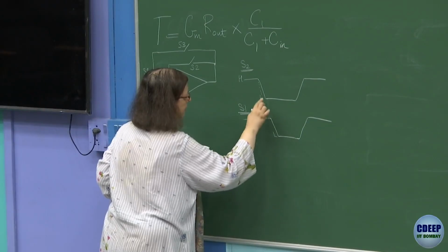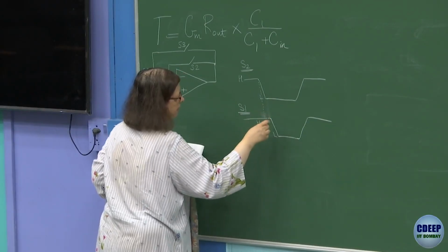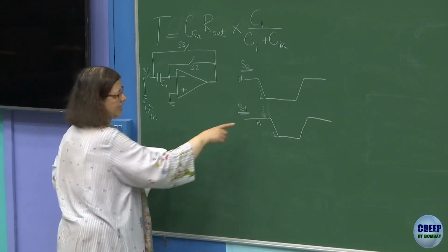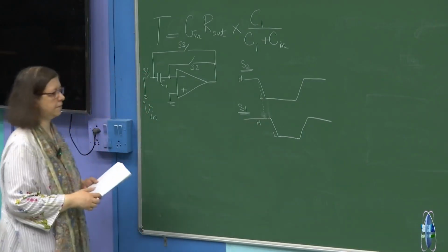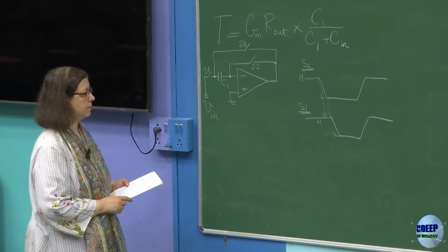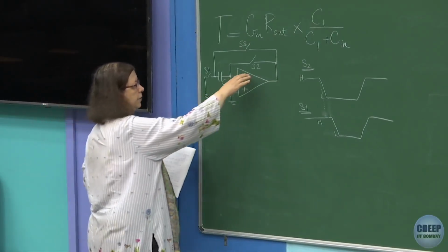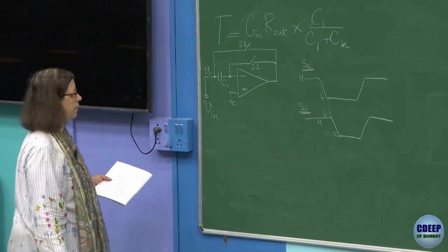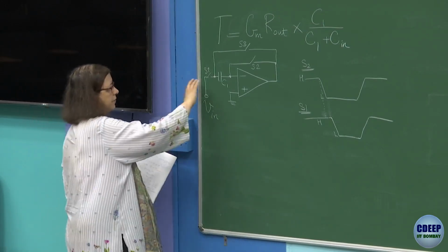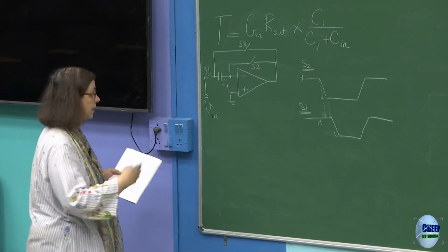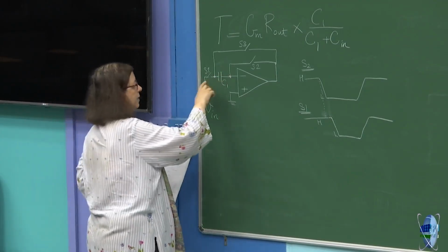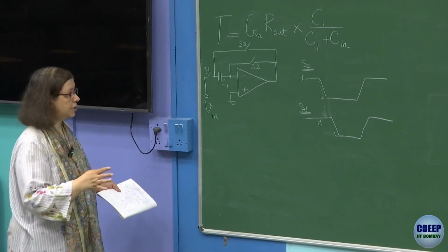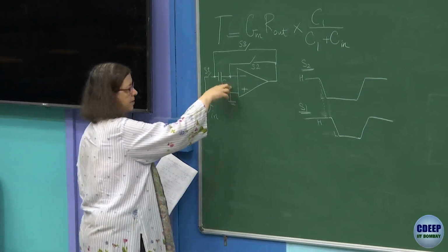In fact, the falling edge of S2 starts before the falling edge of S1, and that was the arrangement. We want to open S2 to create a high impedance path for the S1 charge which is injected into S2. It will not be naturally high impedance because there is a Cin over here.